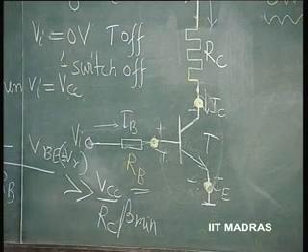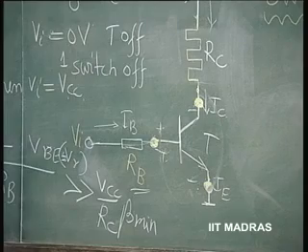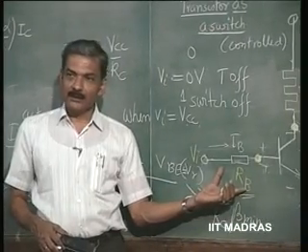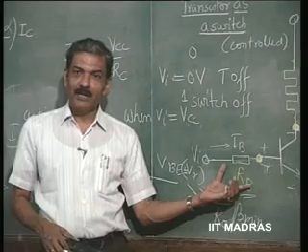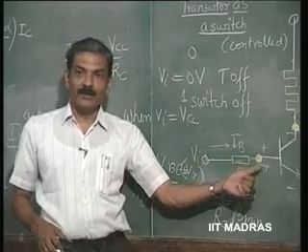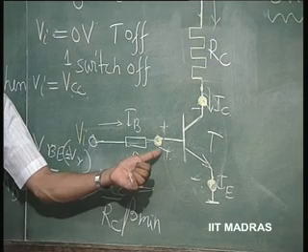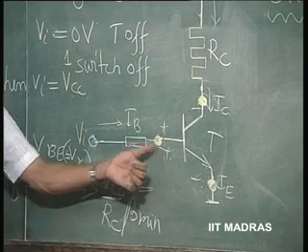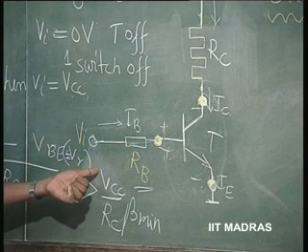Okay. Now, this is unlike an amplifier design, where obviously I will not put any series resistance. A series resistance will cause unnecessary loss in signal. So, Vi is applied directly to the base. In the case of a transistor being used as a switch, only then I will put a current limiting resistance.